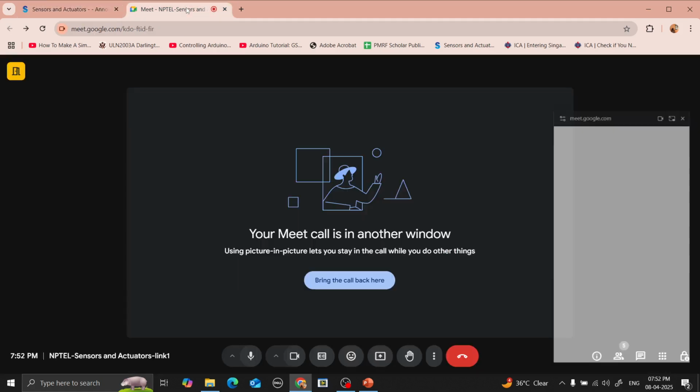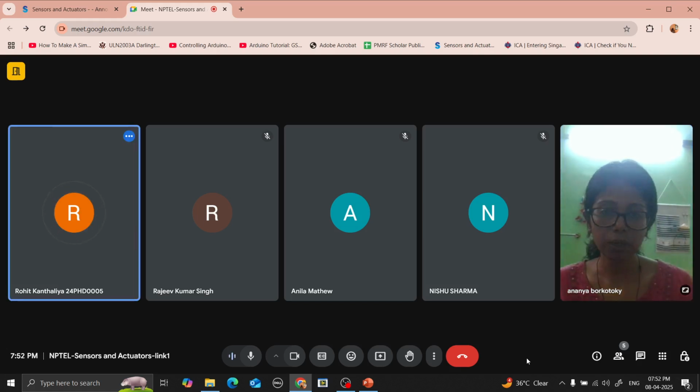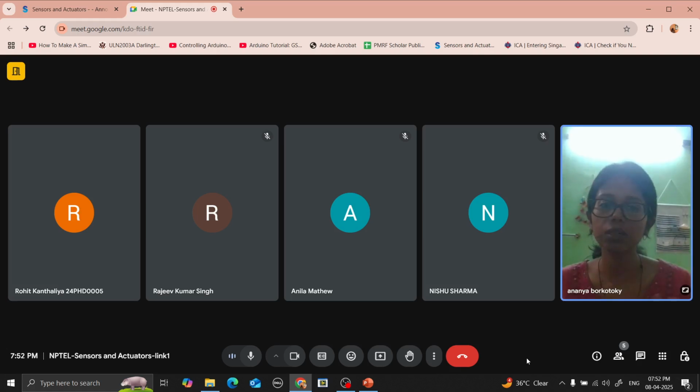What I think is that it is mainly because of the low temperature process. But if the question is specific to some problem, then the team handling the assignment questions will be able to answer. Mostly we use PECVD because it's a low temperature process. And in the example that we discussed today, it is specifically for low temperature because we are dealing with flexible substrates. Flexible substrates usually cannot handle high temperature.